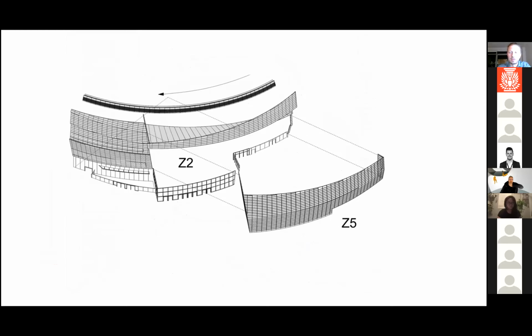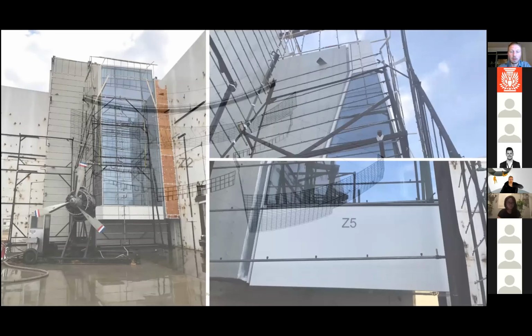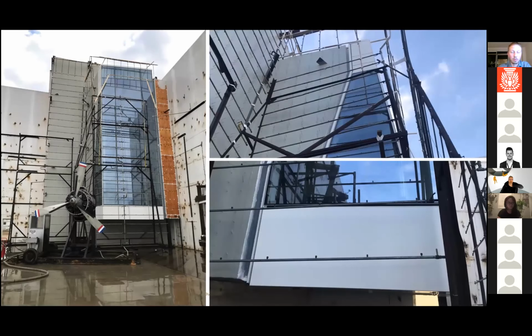If you remember when I showed before how the rain screen is assembled, the structural load path follows the logic of traditional curtain wall, and then there is actually some actual curtain wall also in the building, which are the 2 atria more specifically, that are face sealed glass, long span systems instead, and they need to be mocked up for performance testing. If you've ever been to one of these, it's pretty cool. I hope you get to do it if you haven't.